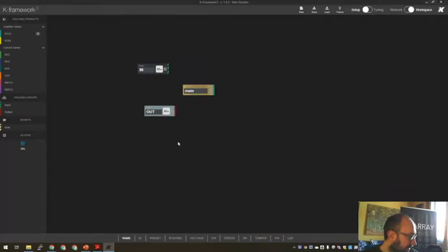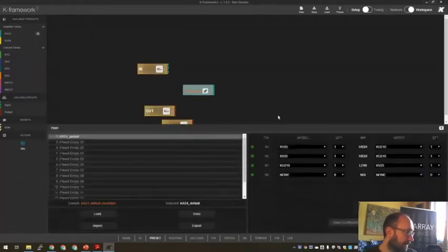Let's do the same kind of example. So I want to group separately the subwoofer. So in this way, the subwoofer is number 3. Because I decided, you can put it wherever you want. So I want a group to EQ the whole system on the output, and then I want another group just to fine-tune the subwoofer only. ID presets. Let's have a look at this on the amplifier.